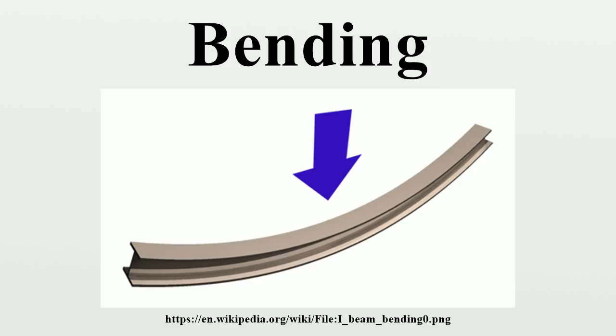The stress distribution in a beam can be predicted quite accurately when some simplifying assumptions are used. Euler-Bernoulli bending theory. In the Euler-Bernoulli theory of slender beams, a major assumption is that plane sections remain plane. In other words, any deformation due to shear across the section is not accounted for. Also, this linear distribution is only applicable if the maximum stress is less than the yield stress of the material. For stresses that exceed yield, refer to the article plastic bending. At yield, the maximum stress experienced in the section is defined as the flexural strength.